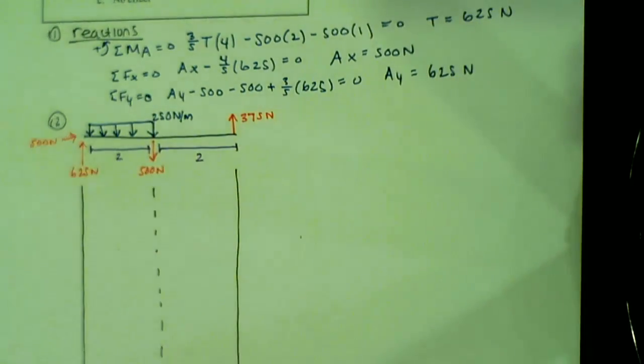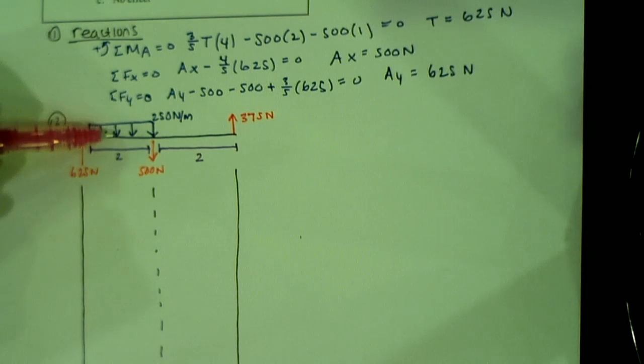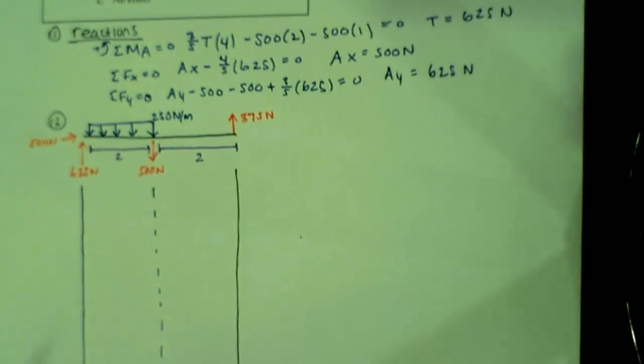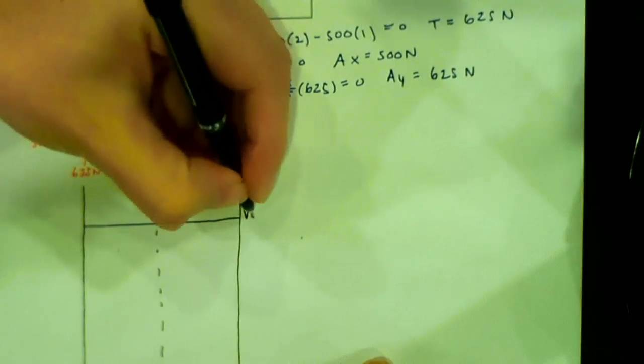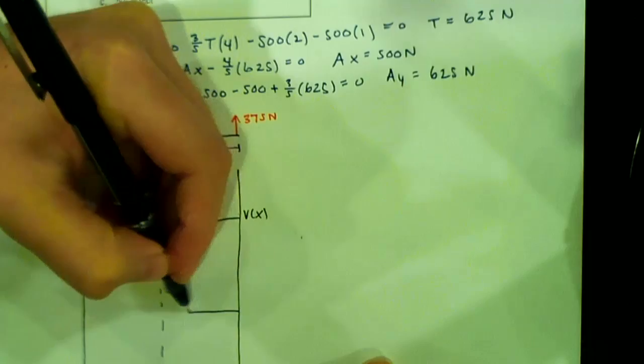So it's at the beginning or the end of the beam, at the beginning or the end of a distributed load, and anywhere you have a concentrated force or a moment. Why didn't I include one right here in the middle of this? Good, that's a distributed load. That force doesn't actually exist there. So we have all our discontinuities. So there's my V of x and my M of x.